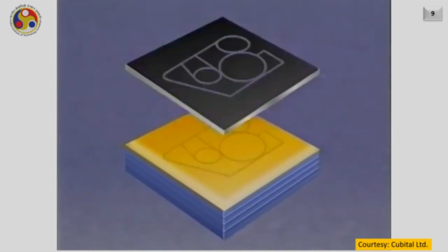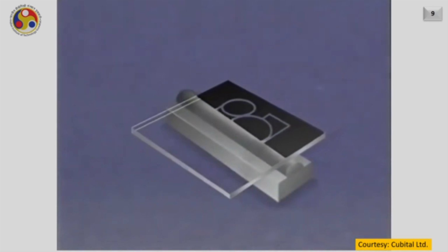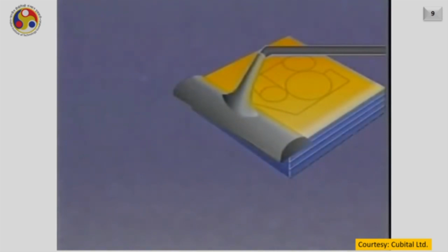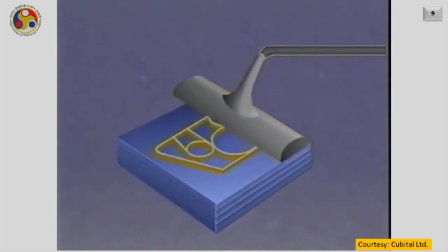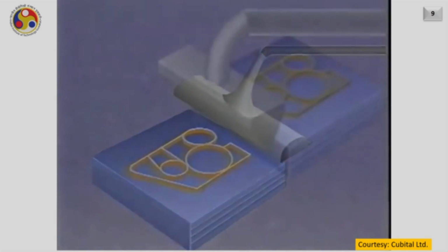As the region where the light passes through gets cured, the remaining portion will be in the liquid form only. Meanwhile, when we are removing the liquid region, the photo mask will be created on the other hand. We wipe off the liquid material, and as a result, you will have a thin wall structure in this particular case.